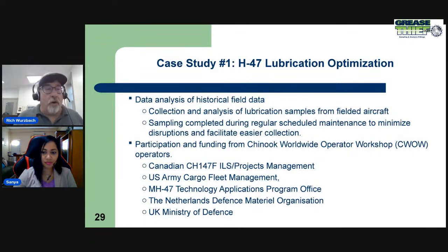This was no different. Over the years, when there were issues, failures, maintenance problems, when they would tear the equipment apart and find things that did not look good, it was often the response to say, well, let's shorten that interval. Let's get fresh grease in there more often. And the logic is, well, grease is not that expensive, and the machine is very expensive, so let's put some more grease in. But we now know that over-greasing is a problem as well. What we truly want to do is optimally grease all our components.